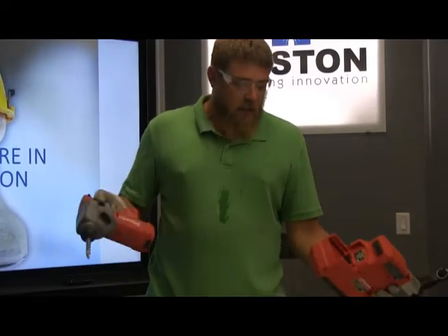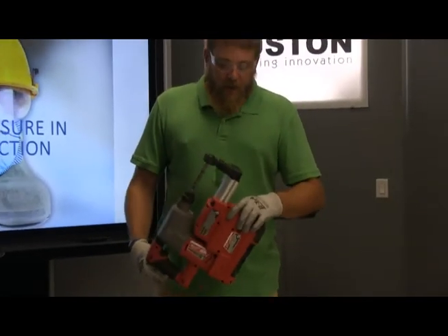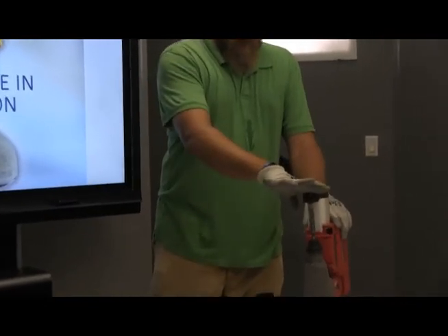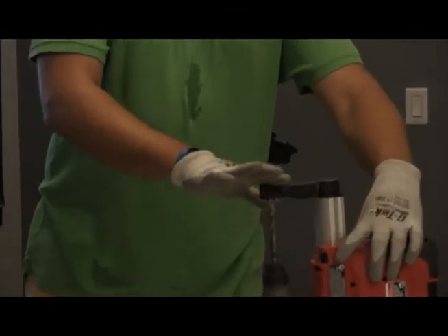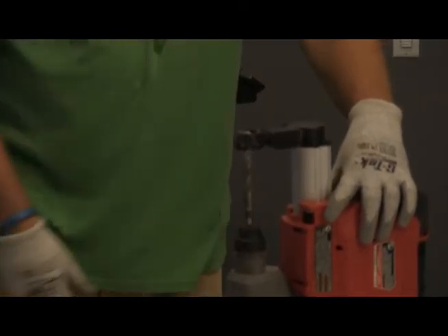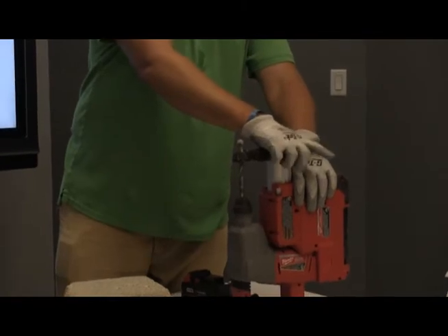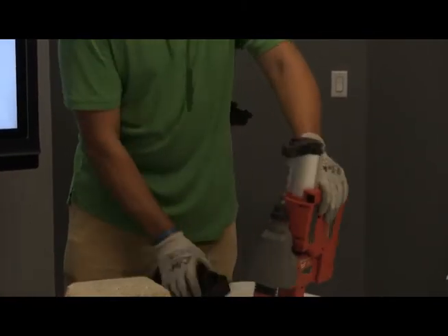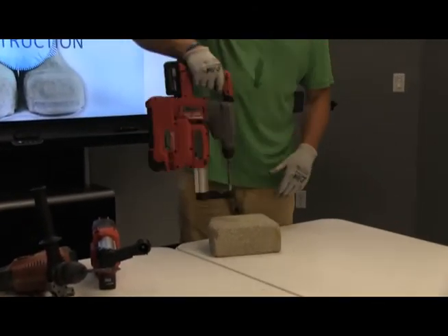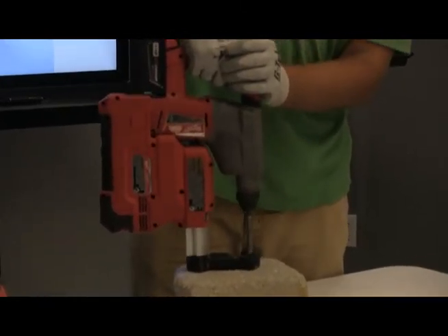Alright, so this unit literally snaps right in. It's all self-contained, runs off of one battery. The only thing that you really have to do after you snap it in is make sure that your dust collection shroud is even with your drill bit, because this is all pressure activated once you are running this piece of equipment. So as soon as this starts getting depressed, the vacuum kicks on and starts sucking the dust out of this shroud right here. So pop my battery in, got everything set, got my safety glasses and my gloves on, we're ready to drill.